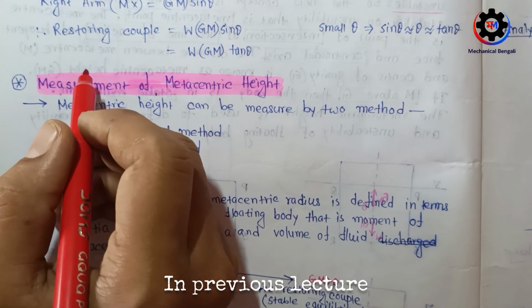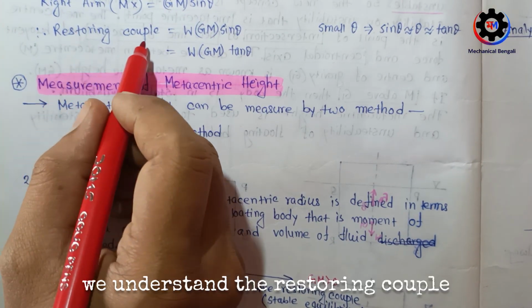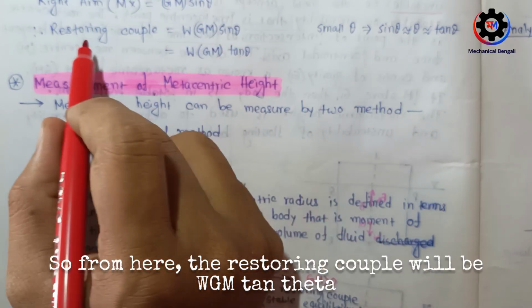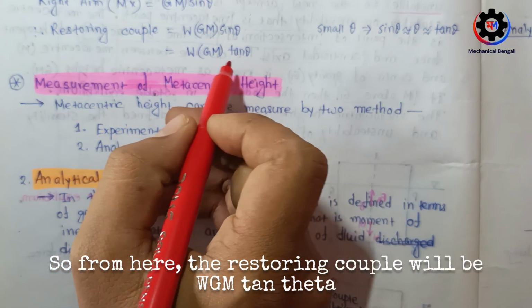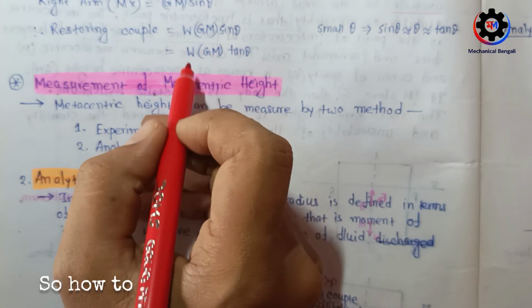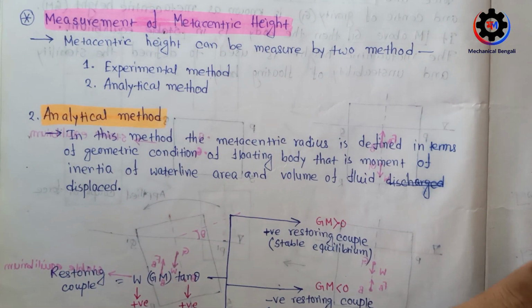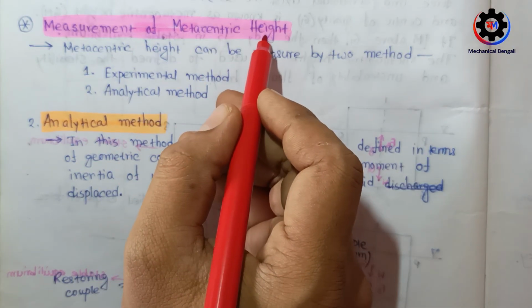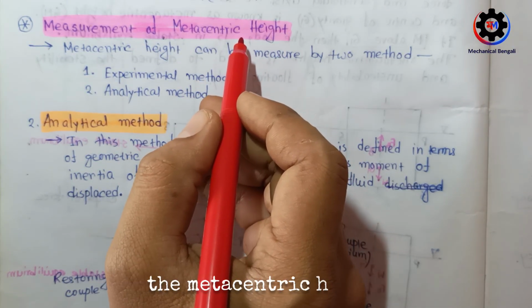In the previous lecture, we understood that the restoring couple is equal to W GM sin theta. So from here, the restoring couple will be W GM tan theta, where GM is the metacentric height. So how do we calculate this metacentric height? There is a process, that is, measurement of metacentric height.